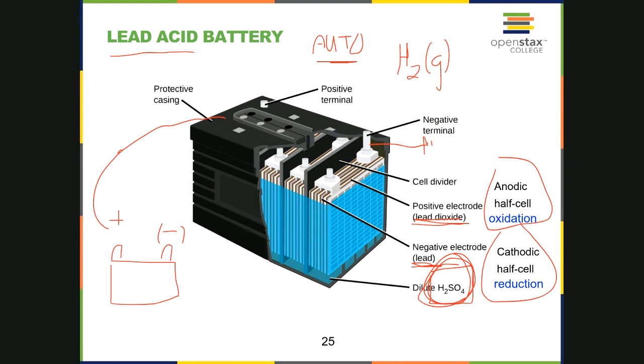So what you would do then is, from the charging automobile, you would run the cable over to another location that is ground, or another metal part of your car, but you want this connection to be away from the battery.